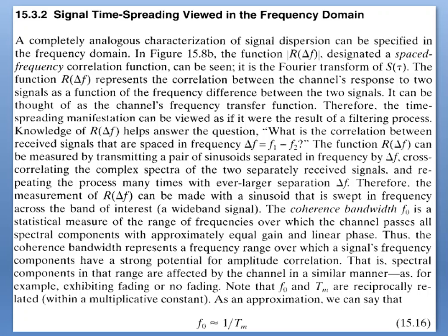For the case of a mobile radio, an array of randomly uniformly spread scatterers with all equal magnitude reflection coefficients but independent, randomly occurring reflection phase angles is generally accepted as a useful model for the urban propagation environment.